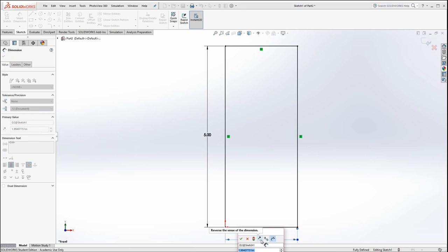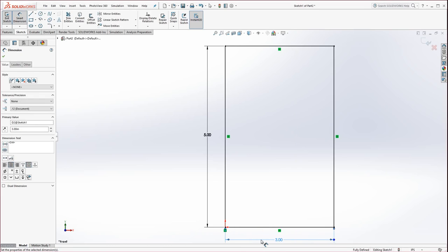And let's go ahead and type in 3. You don't have to type in 3.000 or anything like that. Only if it's a whole number, just 3. You don't have to type in what's after the decimal place unless there is actually something like 3.125 or something. But in this case, just type in 3, hit enter, and it knows to go to 3 inches.